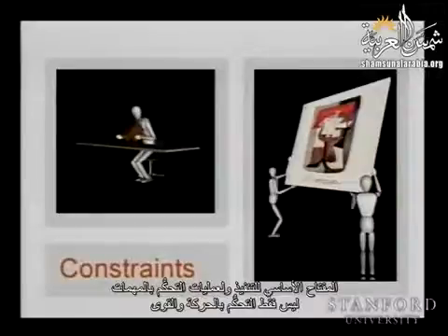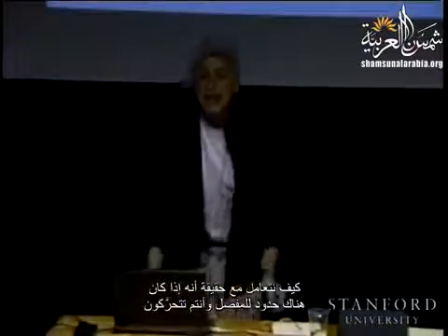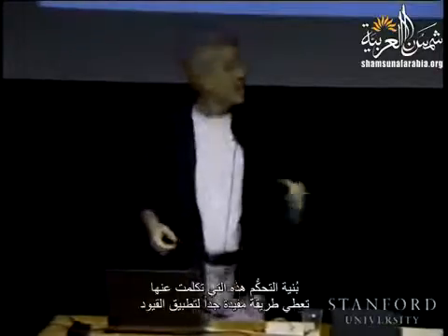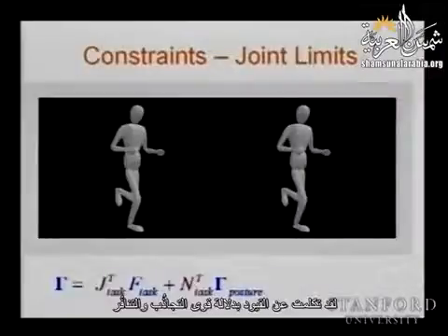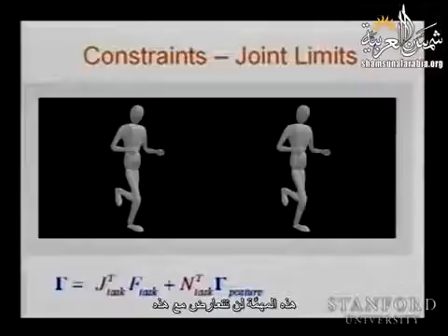and a key aspect of the implementation and the task-oriented control is not only just motion and force control, but how do you deal with constraints? How do you deal with the fact that if you have a joint limit and you're moving and you hit a joint limit, what is going to happen? So this structure of control that I talked about produces a very useful way to apply constraints. Essentially, I mentioned constraints in terms of attractive forces, repulsive forces. Now, if you have a constraint, it has to take the highest priority. In the structure of task and posture control, we have priority. This task will not interfere with this.